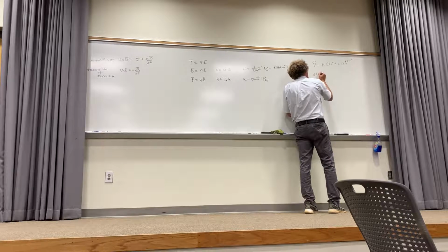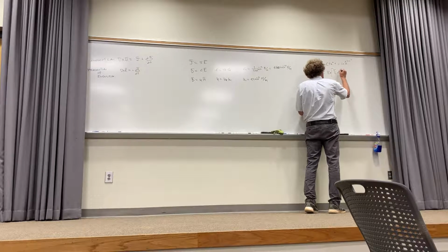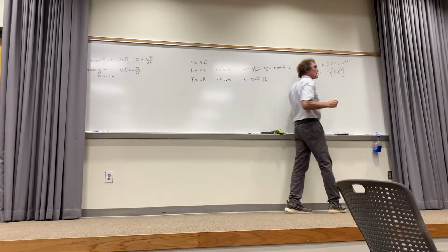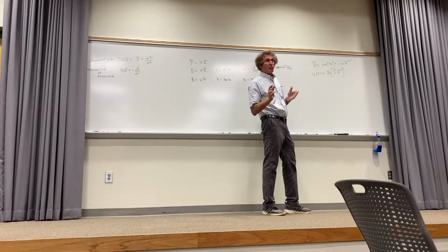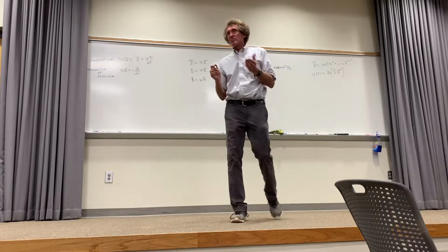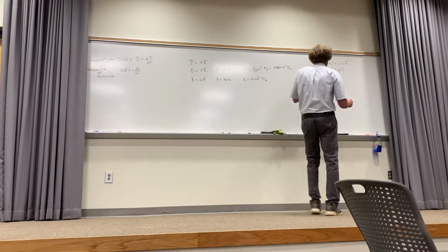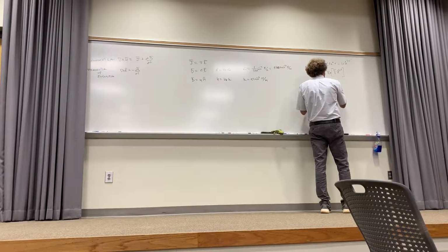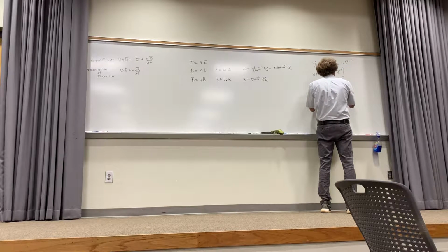Now, if I want the time domain form of this, what I do is take the real part of the phasor domain form times e to the j omega t. Sometimes people don't realize this is what they do, but this is the way you go back to the time domain. We suppress e to the j omega t when we're in the phasor domain. Now we multiply by e to the j omega t, but we have to take the real part, or the projection on the real axis. What it amounts to is the real part, technically in curly brackets, of this phasor, which is 10 times e to the j 30 degrees times e to the j omega t.